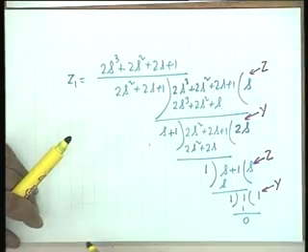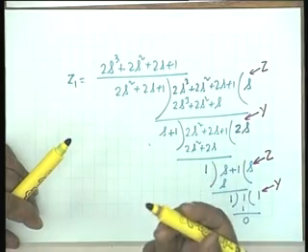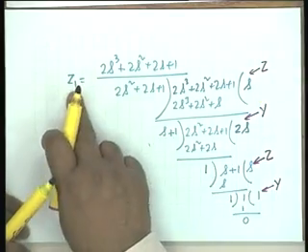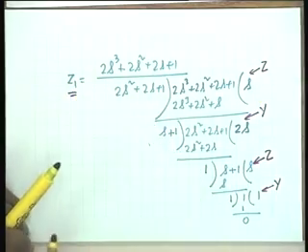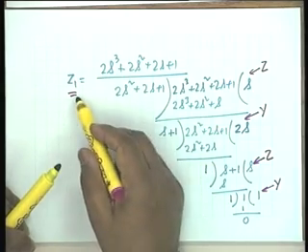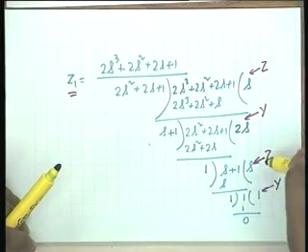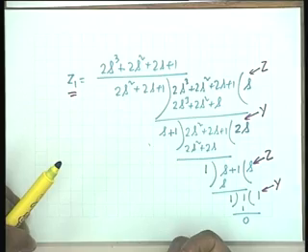Okay. So you must keep track of the dimensions, and the dimensions, as you see, they alternate. Starting with impedance. Why is this starting with impedance? Because the expression is that of impedance. Starting with impedance, impedance, admittance, impedance, admittance. Alright, and the synthesis is complete. Now let us see, any question at this point?